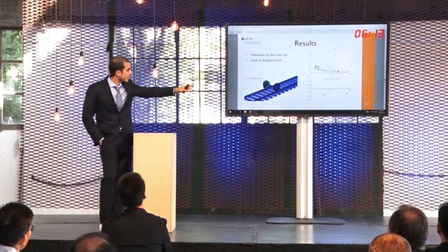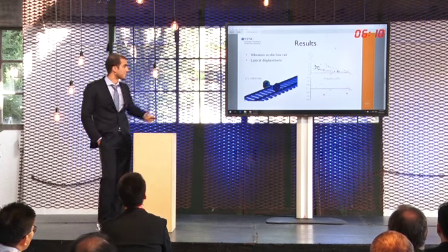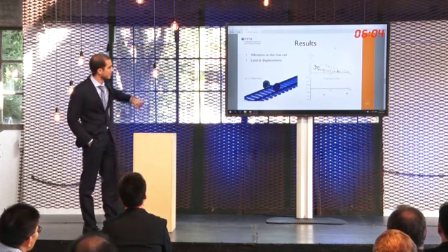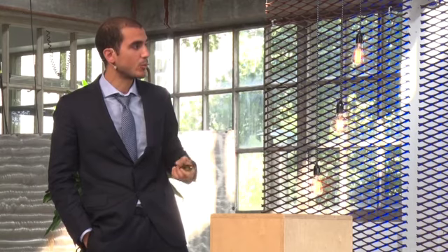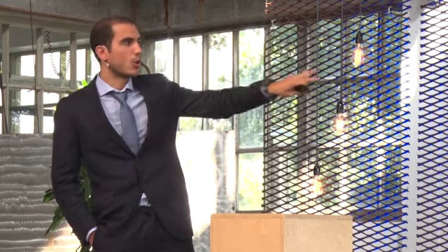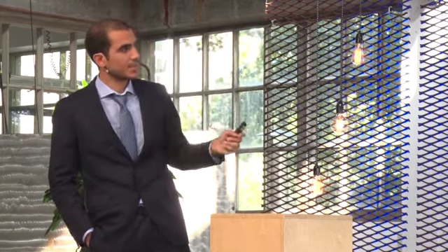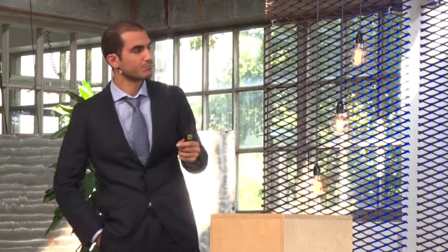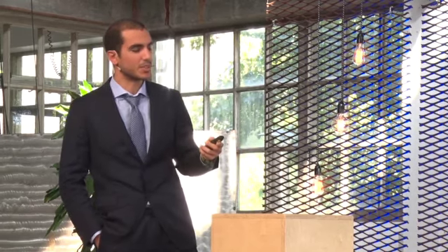If we take into account the first one, which is the lower frequency one, we can look at the mode shape here on the left. We can point out that the vibration is almost all related to the low rail side of the system, and the displacement is almost all lateral. We can point out that this is interesting because there is an accordance with the literature on rutting corrugation.